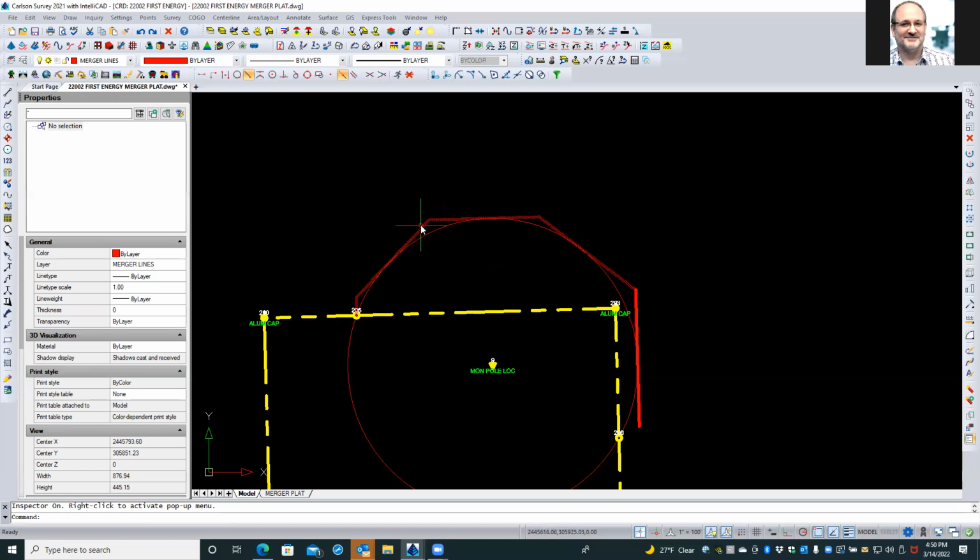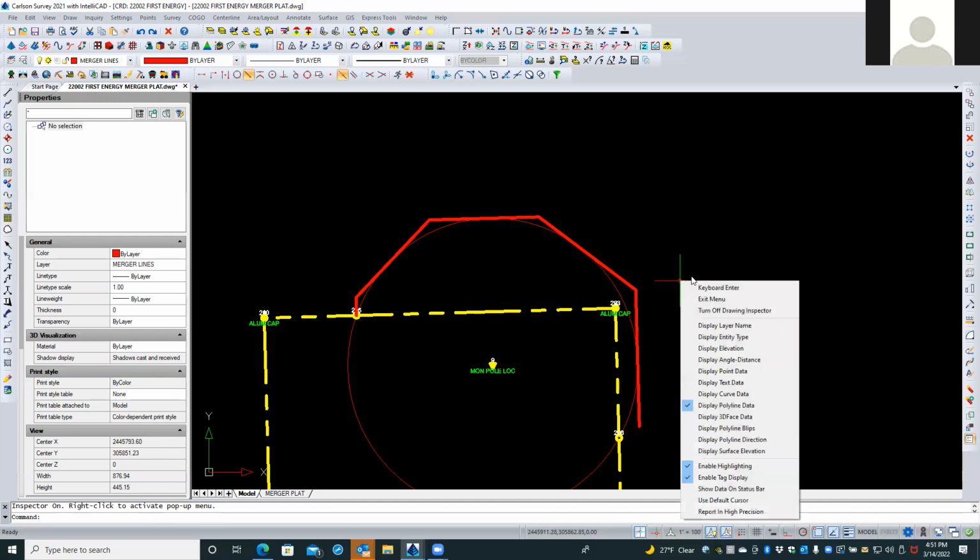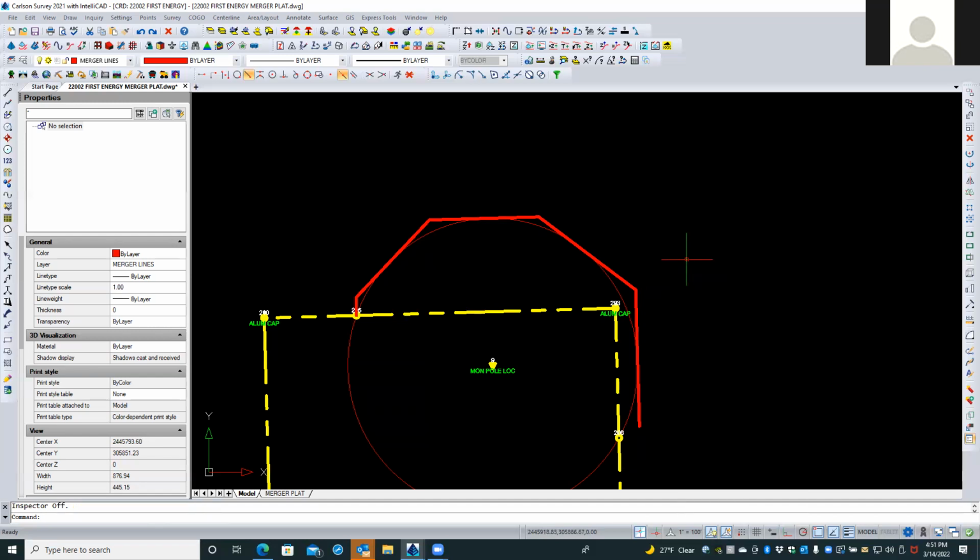This 120.682, that's set because this point is set. The point of tangency is set, and this line up here being parallel to that yellow property line is set. You could make sure that it goes out to that same distance. Now, right now, it's actually longer, so if you wanted to match that distance of 120.682, you would be pulling this point back in 4 feet, which would pull this point up higher. So, you know, maybe that's not the approach. Maybe, I think the thing to do is just let them take a look at the sketch. When I met the engineer out there, he pretty much indicated that the only critical dimension was 165 feet.